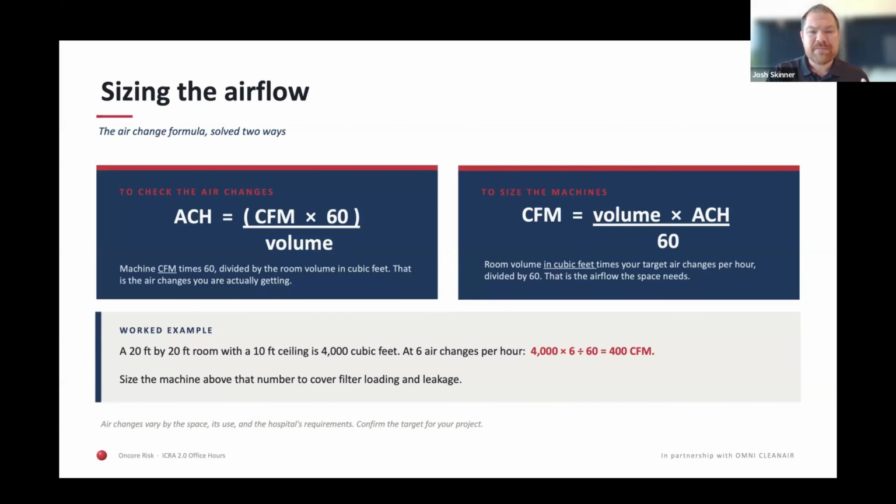So I agree with you, less machines that are pumped more is better. And I always encourage give yourself some wiggle room, give yourself the ability to go up and have more CFM capability than what you think you need, because you're oftentimes building this whole calculation off of a false number. And that false number is that peak number. What a company will advertise a machine as, like, great, it does this, but that's actually not what it's doing all the time. That's what it's doing at its very best. And instead understand what that machine is. Do I suggest a preference? I tend to suggest 1 or 2 larger machines versus 15 smaller machines is probably the better route to go.